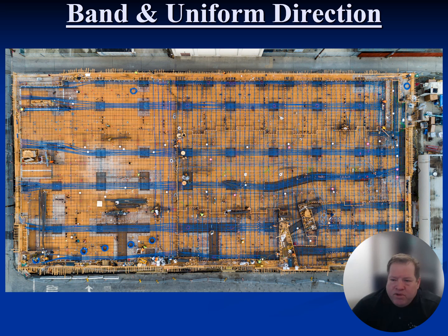The other thing that's great about this photograph, I think, is it highlights some of the beauty of PT that you don't get across with the numbers. If you look at this band right here, let's say we have 25 strands, they're continuous all the way across the structure. So with all the load on continuous reinforcement, its ability to share the load and redistribute between spans gives you a lot of potential in those segments, because there's no lapping, it's active reinforcement, and it is one continuous rubber band across that structure. So you have a lot of potential there.